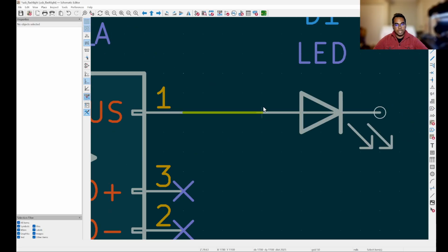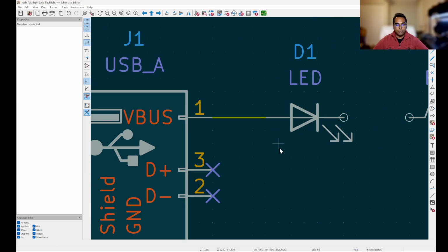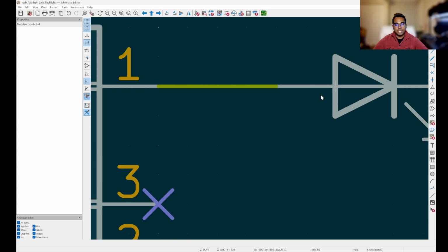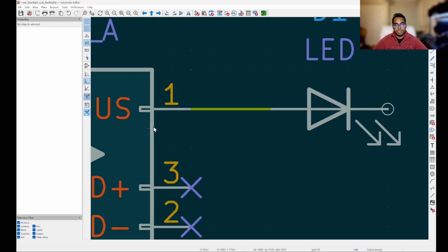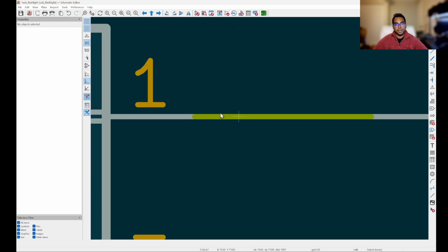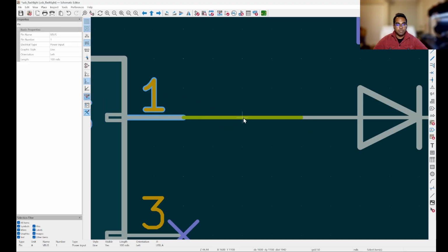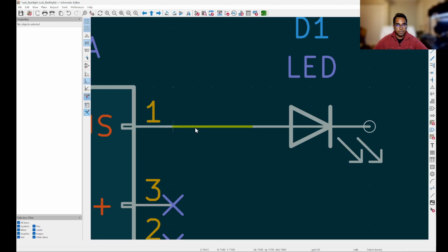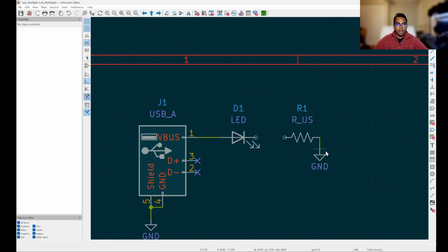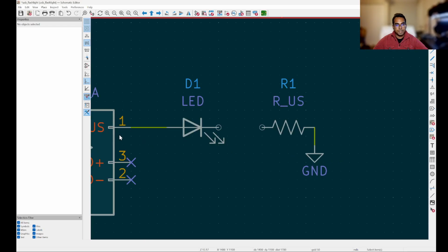You'll notice that there are no dots here, and I said earlier that if there's no dot, it means that no two wires are connecting to each other, but that's because these aren't wires. This is a symbol, and the connector is another symbol, so the wire isn't intersecting with another wire. It's not showing you that two different wires are connected. The fact that the circle disappeared on the pin of each one of our components means that this wire is in fact connected to it.